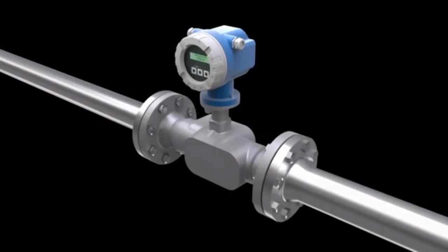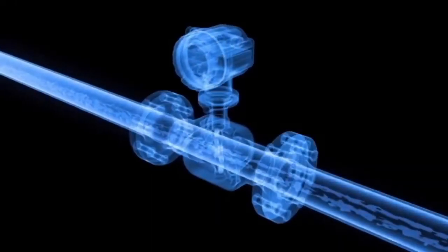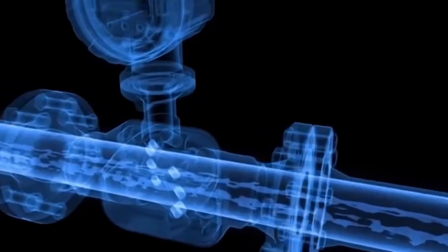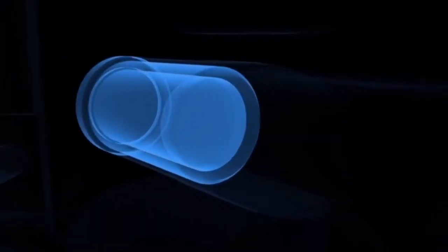Here is how the measurement method works. Inside the ultrasonic flow meter, pairs of sensors are fitted across from each other in a measuring tube. Each sensor can alternately transmit and receive an ultrasonic signal. Simultaneously, the transit time of these signals is measured. The ultrasonic signals are generated by piezoelectric crystals when a voltage is applied. Conversely, a piezoelectric crystal creates a voltage when an ultrasonic signal impacts the sensor.